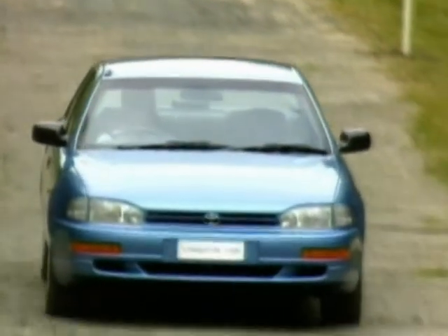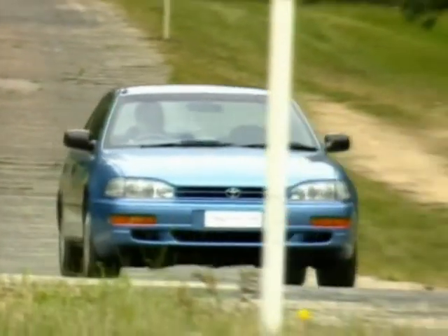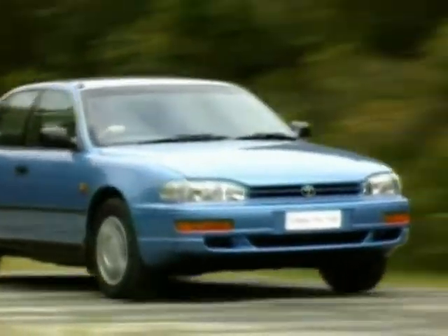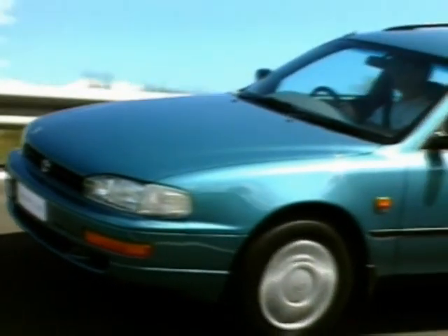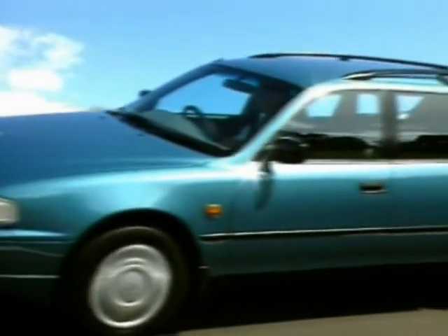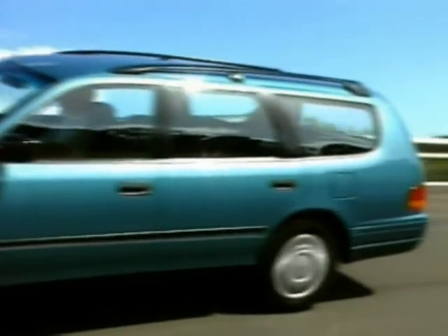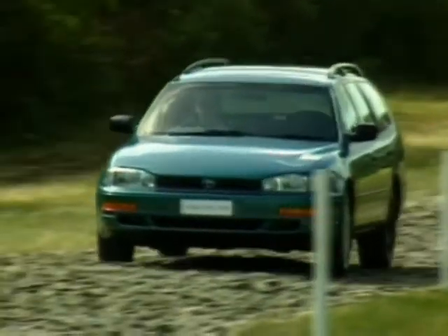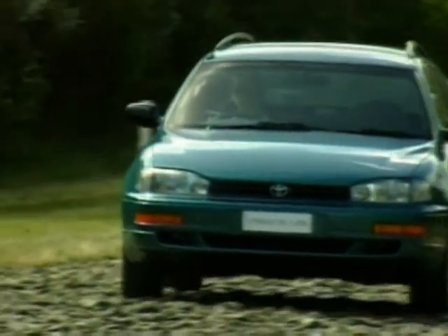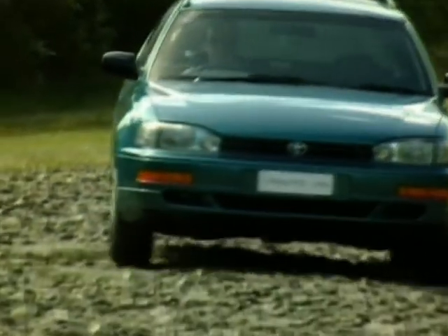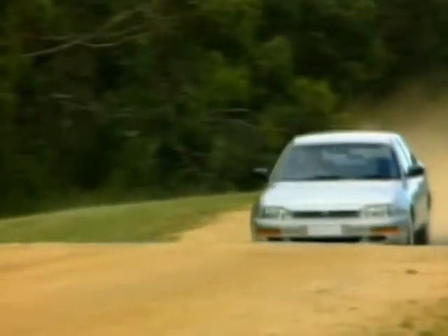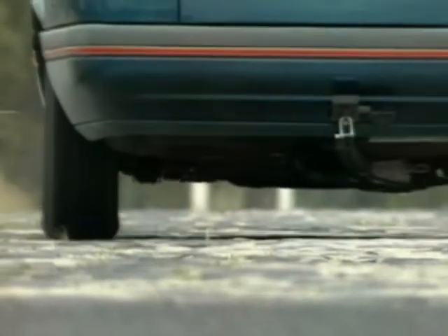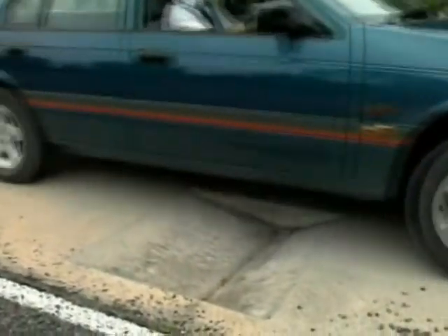This section examines basic principles of light vehicle suspension systems. The suspension system isolates the body from road shocks and vibrations which would otherwise be transferred to the passengers and load. It also must keep the tires in contact with the road. When a tire hits an obstruction, there is a reaction force. The size of this reaction force depends on the unsprung mass at each wheel assembly.